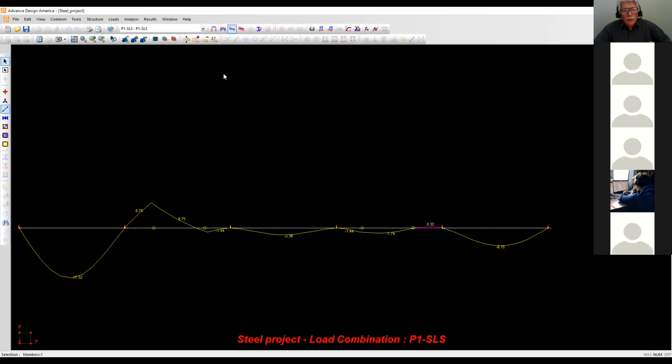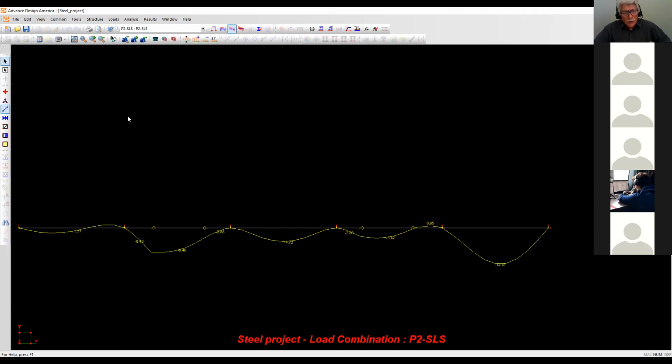Then after that, you go to P2 and look at the deflections under P2. So serviceability limit states P2. And there it is. Oh, look, nothing exceeds 27.7. I'm good for P2. Right click, print, and print this one. And at the end, guys, if you want to make it really nice, you go to the lab and take the PDF editor in the lab, -2H27. If you don't want to have thousands of sheets, you can combine these all into one PDF and just put it on one sheet. It's going to save you, you understand? But it's up to you.